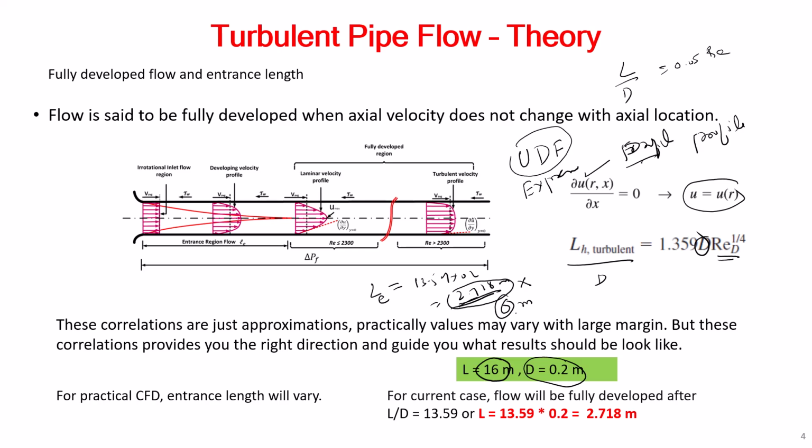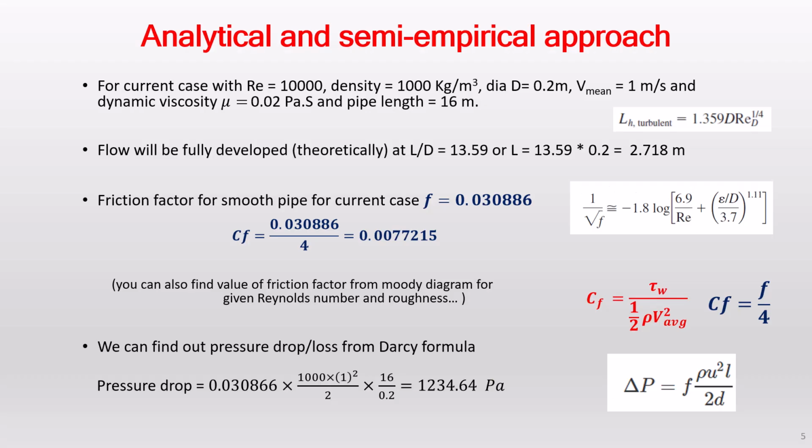And the UDF is the ultimate option, where you write C code and couple it with Fluent. So I can model only a few meters upstream and apply this profile exactly on that portion, modeling up to here and applying the velocity profile there. Whatever profile I want to model, whether a laminar profile or a turbulent pipe flow profile, this will shorten the length, and I can add only 5 to 10 meters and solve the problem, because we are always interested in the fully developed region.